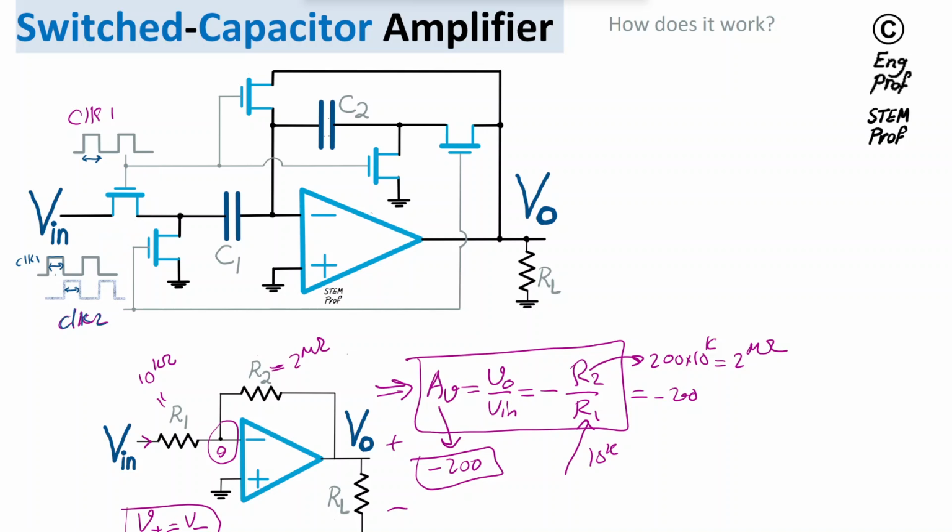So effectively, when this MOS switch turns on, from the perspective of the circuit it's like a short. And when it is open, during the time that clock 1 is off, this transistor is like an off switch with infinite resistance. So we are modeling this MOSFET or NMOS switch as an ideal switch in the circuit. Okay, so when clock 1 is high, this switch is on, and therefore we can model it as a short.